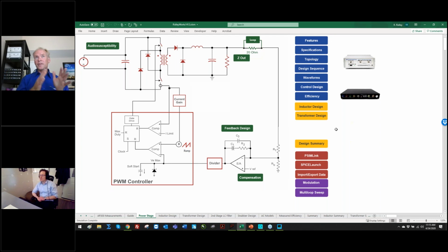The only reason we stop there is because there's a fundamental shift in design strategy. You go 100 kilohertz or 200 kilohertz down at 100 watts, and you start dropping down. When you hit 10 kilowatts, you can still be doing 20 kilohertz, maybe 50 kilohertz. When you get much higher than that, you make this quantum change. Okay, I'm not going to switch at 100K anymore. I'm going to go down to 5 kilohertz.